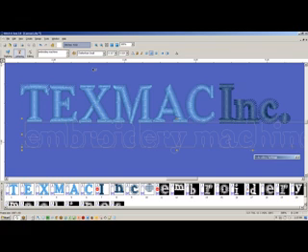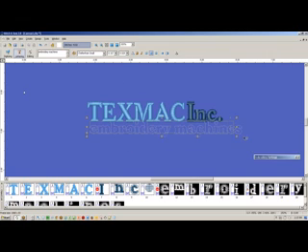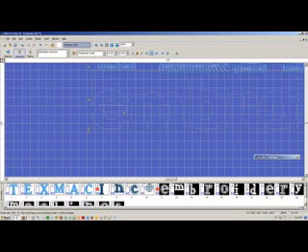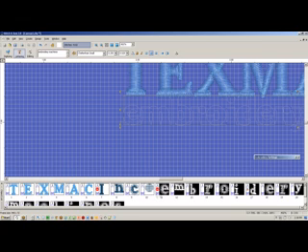Let's see what happens. Okay, so now I'm going to try and size that down, and let's see if that's viable. It still may not be. We've got nice wide stems, but if we go to our 1 millimeter grid, you can see that this is a little bit more open, so this has a little bit better of a chance. I would say you can sort of try that because the holes are at least 1 millimeter block wide. The M here is a little close, but then again, you don't have stitches down here, so I would say you could try this.